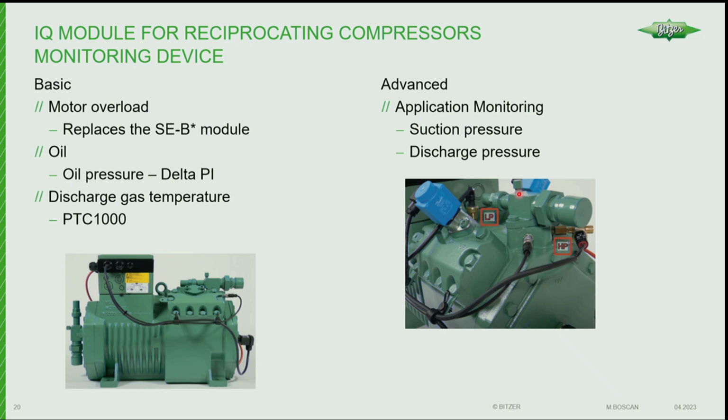So this might be different values than what you have on your suction header and discharge header, because your suction header and discharge header are however many equivalent length feet away from your compressor. All we want to do is make sure that we know what our compressor is doing so that we can help protect it longer and make it last longer, make it run more efficiently.